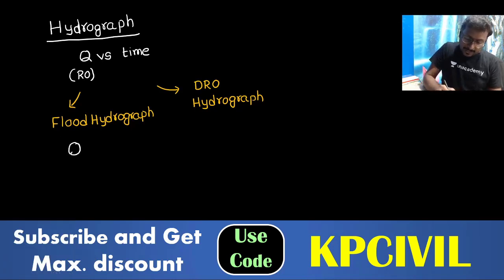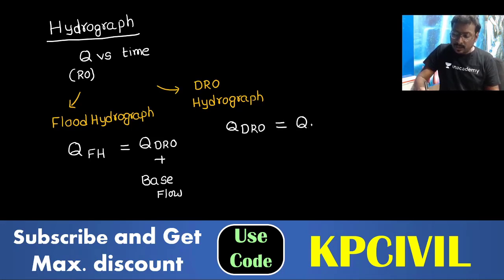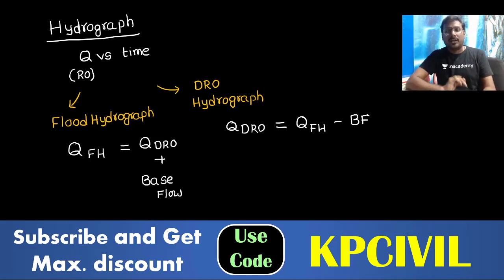Flood hydrograph is taken as QFH, which is the sum of direct runoff discharge plus base flow. Direct runoff hydrograph is purely QDRO, discharge through direct runoff only, after subtraction of base flow from the flood hydrograph.